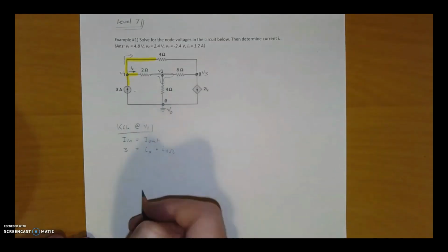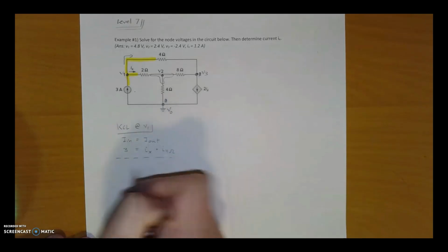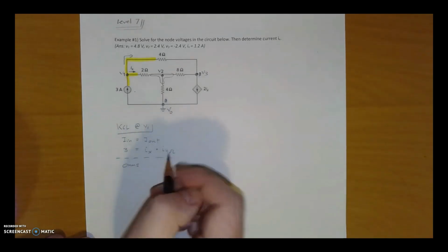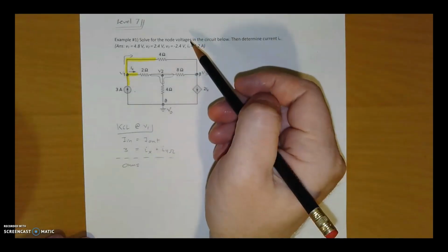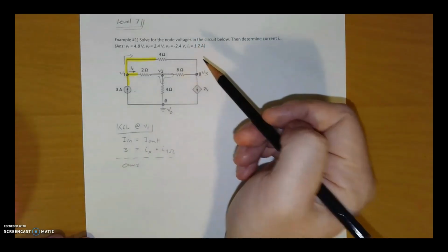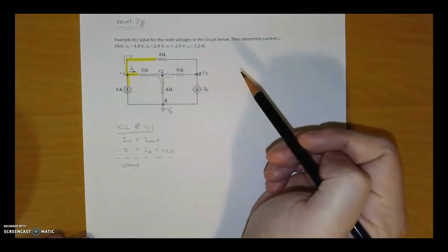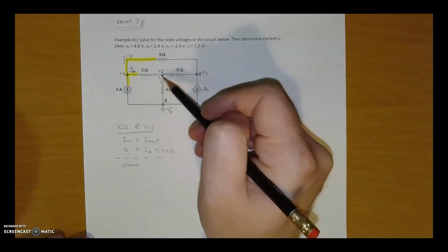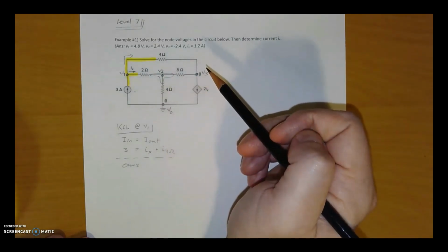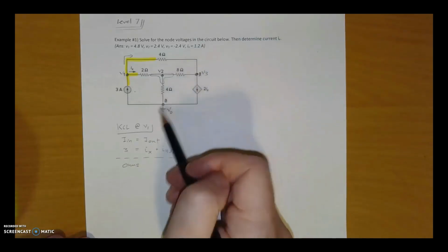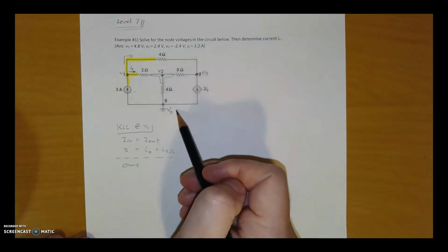Now these I's we can sub out using Ohm's law, because we really don't want currents here. The whole point of node voltage analysis is to have a bunch of equations in terms of our node voltages. So our variables in this problem should be V1, V2, and V3. Those should be the only 3 that we have. Because we have 3 different variables, we're likely going to have 3 different equations, 3 unknowns. We do technically have this as an unknown, but we assume that this is 0.